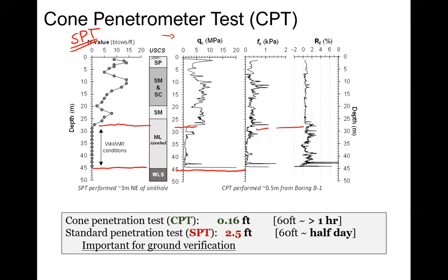So the cone penetration test is really popular in areas where you're expecting this loose material or very soft clay. And you can also see just by looking at the graph that we're interpolating the strength values at, in this case, every couple of meters. But with the CPT, we get a lot of data with depth, and we can clearly discern between soil layers. Like this, for example, we can see this soil layer is obviously a specific soil layer where it gradually increases and decreases. So it's much more sensitive.